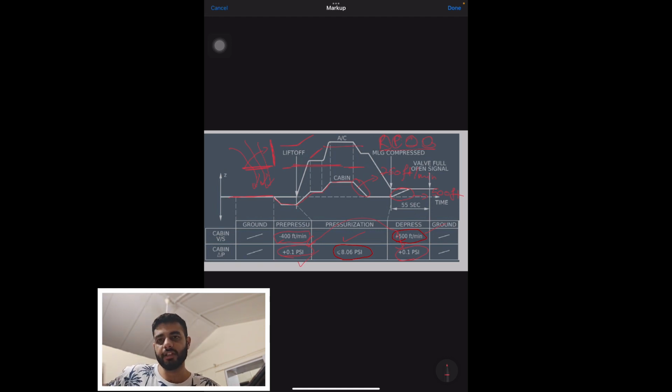Now finally we have the ditching push button. Now the ditching push button is a little tricky topic. Little tricky meaning when you press the ditching push button, you are telling the aircraft, I am planning to put the aircraft down in water. Okay, I'm going to float it on water now. So there is a line which I had shown you, which is called the flotation line. Below this, the aircraft is actually below the water level. So the issue is that if you leave these valves open, water can flood into the aircraft. So the ditching push button automatically closes these valves.